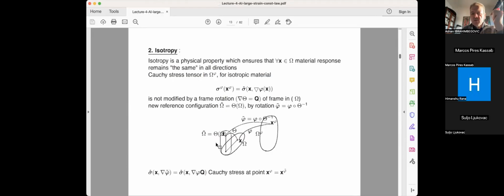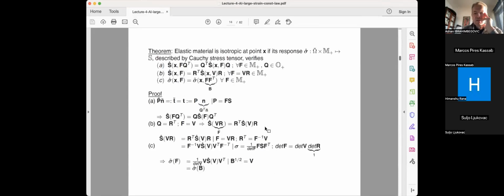If I now go back to isotropy, that means you have the same response no matter what the orientation of the fiber I'm looking at. So what we will do there, again, you can say, well, this different way of writing my constitutive model is given here, and I should have the same result even if somebody has a different point of view of the initial configuration, and you have this rotation slapped on top of your initial configuration. So they should all be mapping the same deformed configuration into the same constitutive law that enters into this.